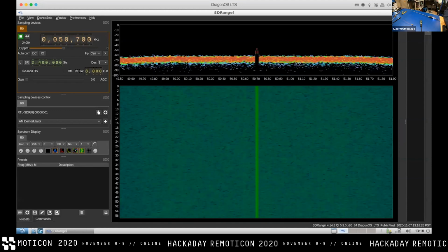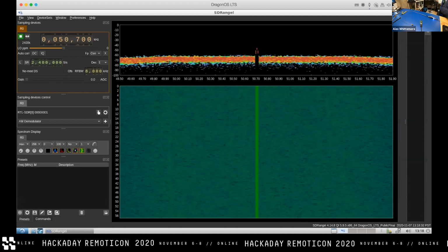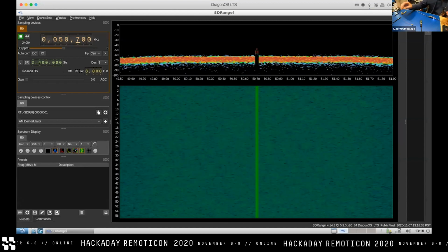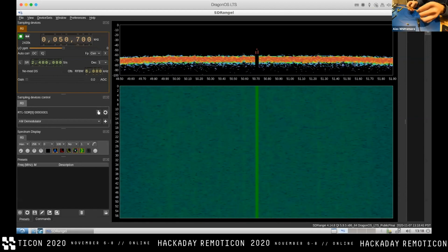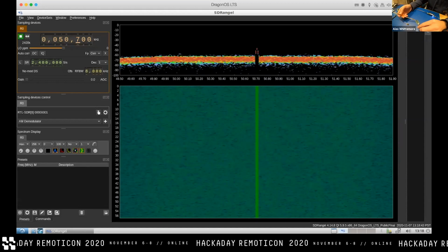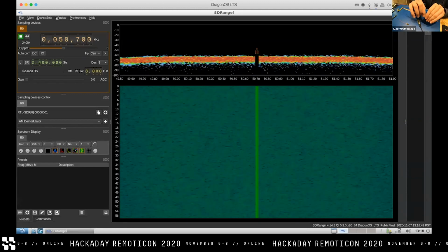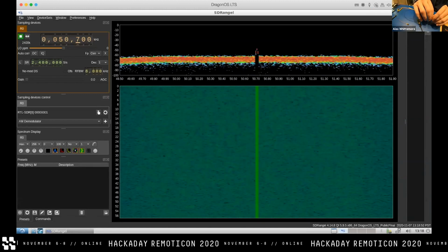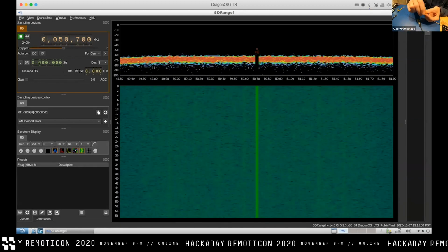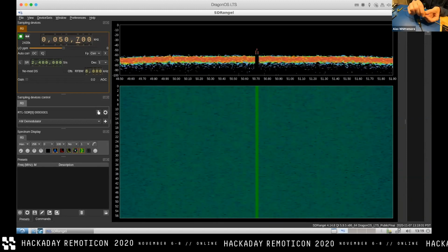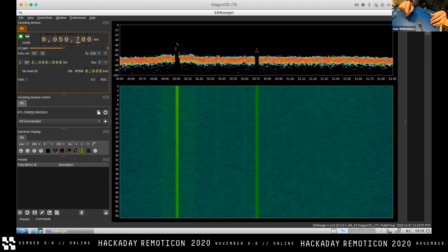Okay, so we've got 50 megahertz. 50 megahertz is over here. So we already know that I basically just attached a PLL output on the chip to some pin over here. And if we start waving this wand around, this one has very limited, you know what, we're just gonna start with the big one. Do it the way that we would expect. We know from the test report, the imaginary test report in this case, that we failed on some 50 megahertz noise coming loudly from somewhere. We attach the big probe and start to try to look around where it might be.